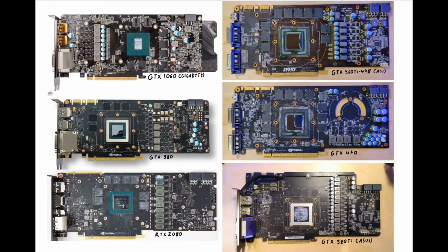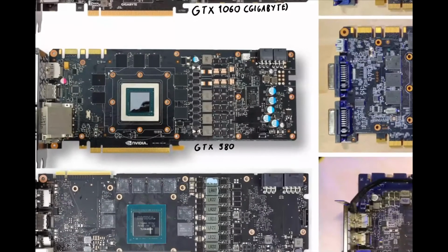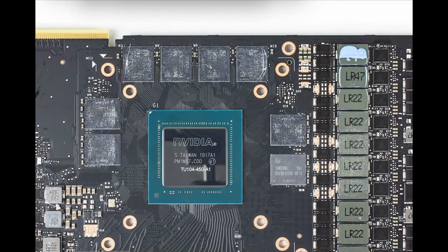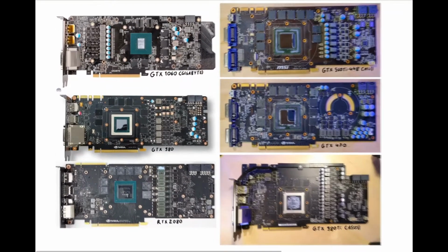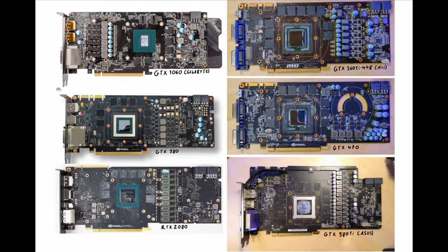There is another version of video memory, which I do not have here on a picture. That is HBM, and HBM is also video memory, but it will not be in the form of a black chip on the PCB like this. It will be integrated into the GPU, so you will have little dies right next to the GPU die, or in the case of an RX Vega from AMD, you have 2 larger ones down there. But HBM is pretty rare. You mostly see it on data center focused, server focused GPUs from NVIDIA, and the Vega graphics cards from AMD, and also the Fury graphics cards from AMD. Other than that, you will pretty much always see GDDR video memory.